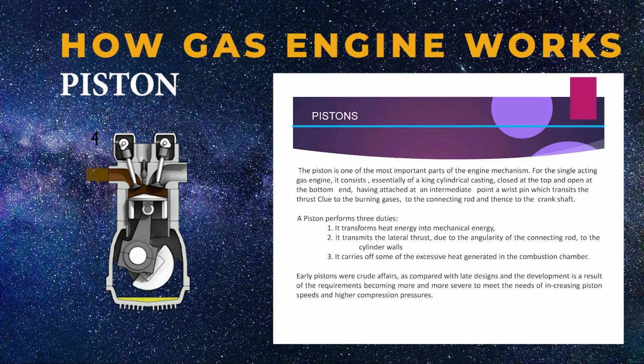A piston performs three duties. 1. It transforms heat energy into mechanical energy. 2. It transmits the lateral thrust, due to the angularity of the connecting rod, to the cylinder walls. 3. It carries off some of the excessive heat generated in the combustion chamber.